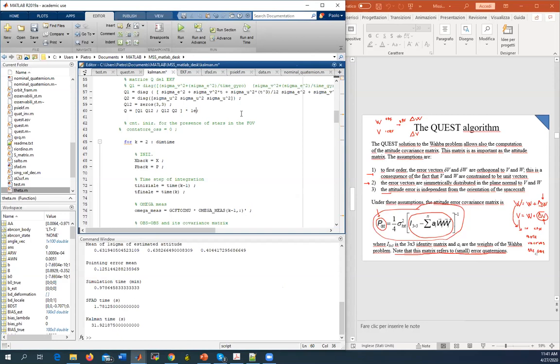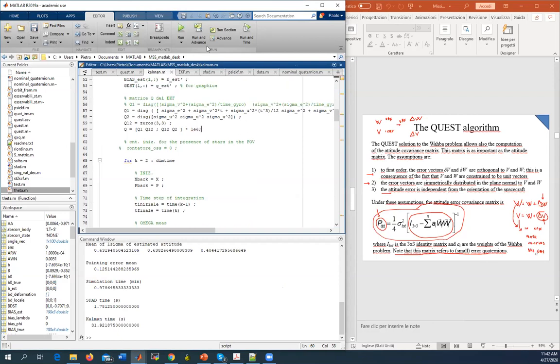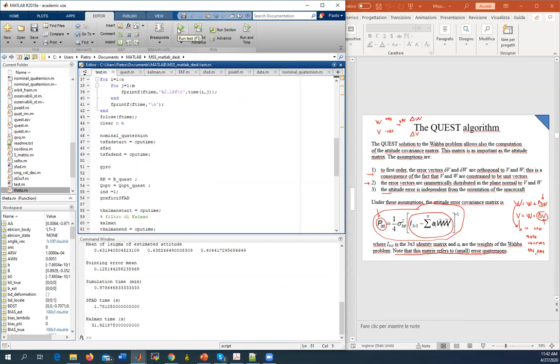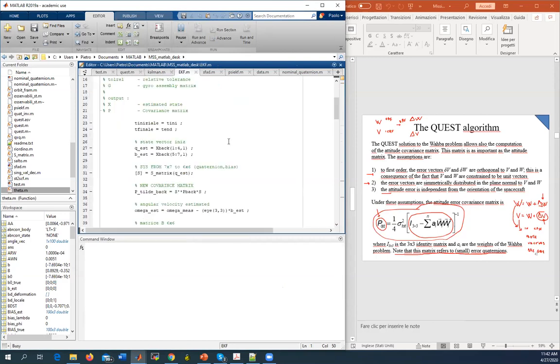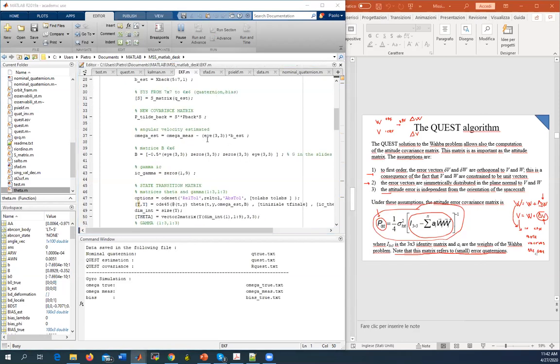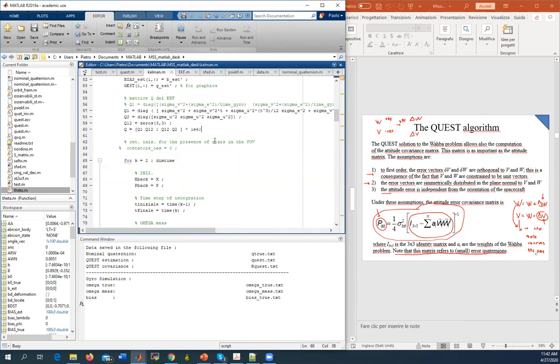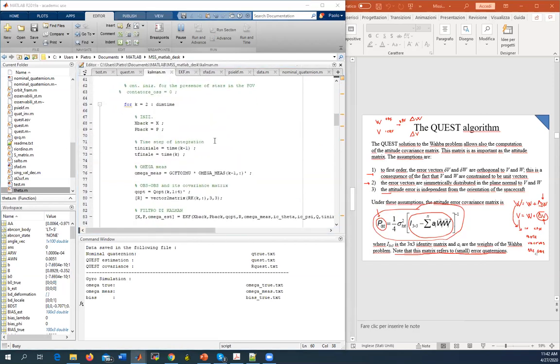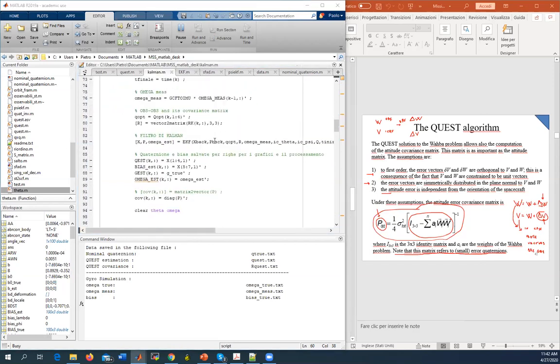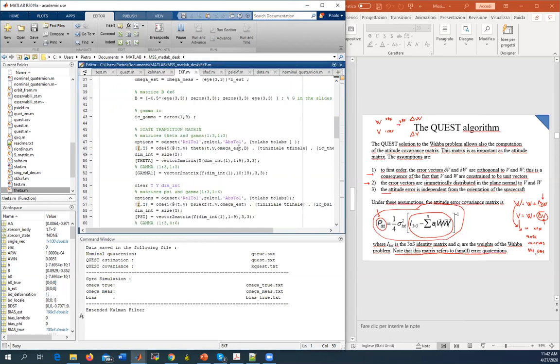So probably, in order to do something correctly, you can try that. It could be a useful and interesting result to show in the homework if you do the Kalman filter: if you fix the Q without propagating it, by using a fixed value of Q, you can probably see this effect even larger.